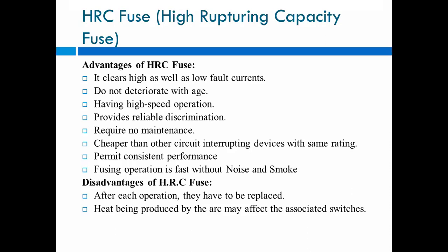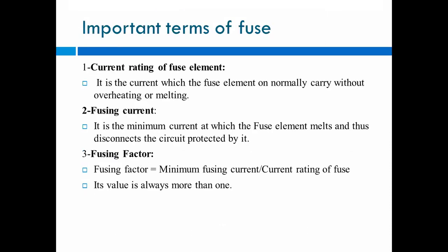And there are some disadvantages of HRC fuses. First, after each operation they have to be replaced, and heat produced by the arc may affect the associated switches. This is the disadvantage of every fuse, because we have to replace it when the conductor melts there. Okay, then the next point is important terms in this chapter.